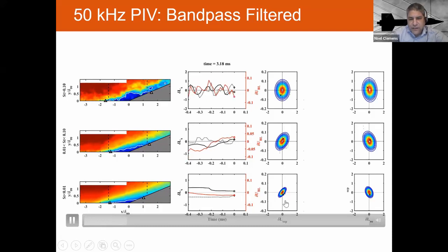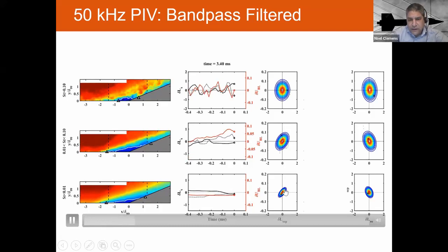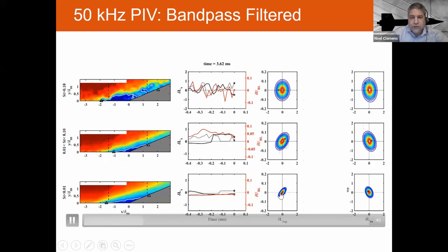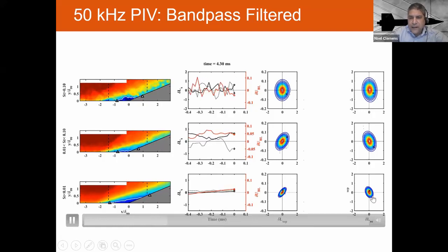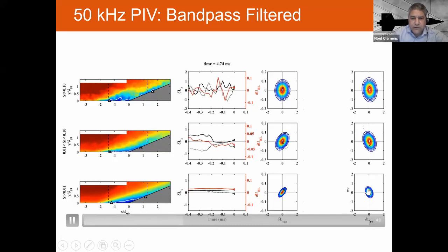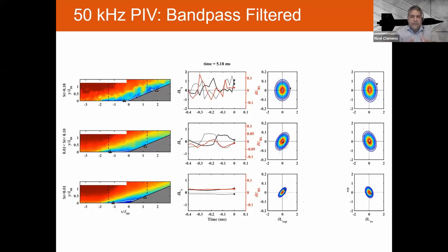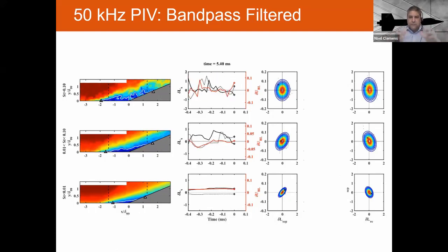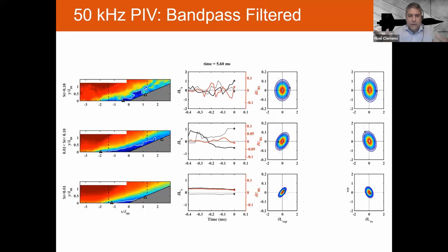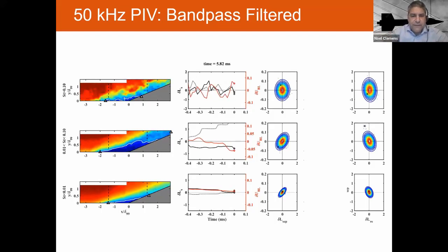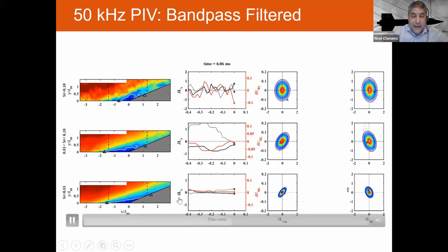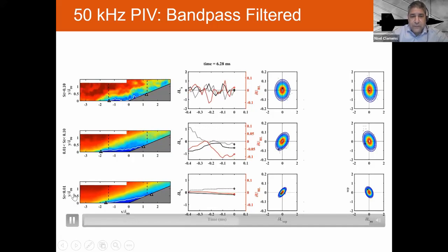And what you see is a very diagonal looking joint PDF, showing there is a strong correlation between the upstream boundary layer fluctuations and the separated flow length scale. And it's also anti-correlated with reattachment. So that's showing that at the very low frequencies, it's just breathing, it's pulsating like a bubble breathing. And in fact, it's strongly correlated to the upstream boundary layer.